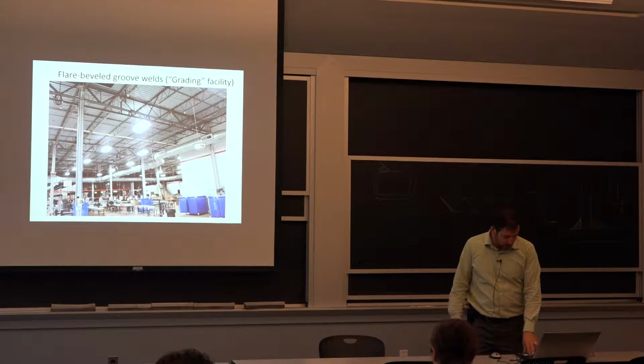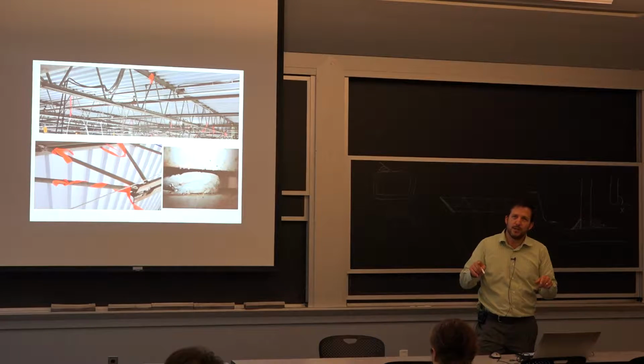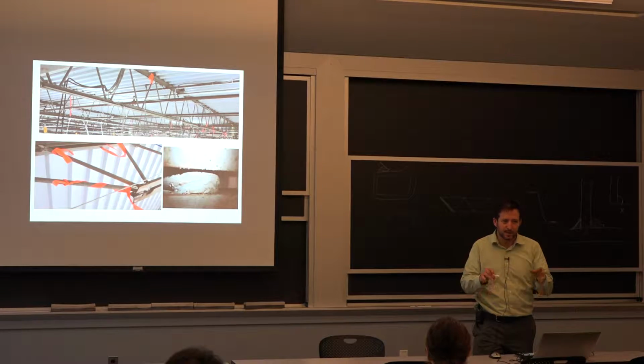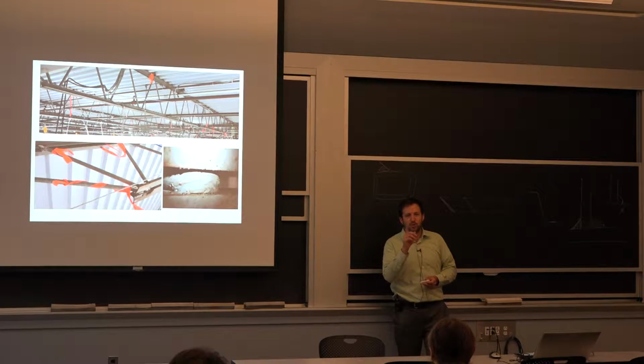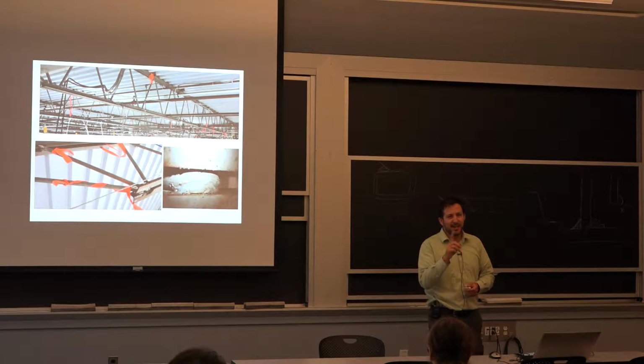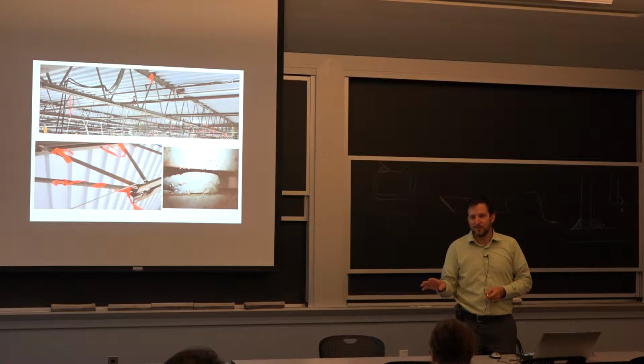It happens over and over. I think I had a little summary sheet. I've looked personally at maybe 15 different roof collapses in a period of only 1 or 2 years when I was working for a structural engineering firm. There was one case where the size of the member was insufficient. Everything else was an issue with the joints.